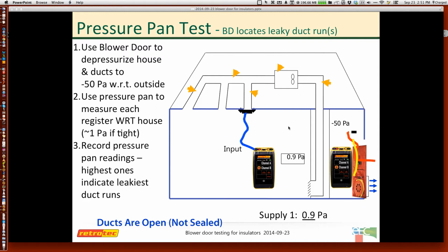If you're looking at existing homes, a lot of programs out there that HVAC contractors actually use something very similar. They get the blower door going, and then they go around and determine which ducts are leakiest. And they feel as though many times you don't need to do an actual duct test when you know where your significant leakage is, and you now know where to focus because you're going to seal the ducts anyway. So now I actually know that I may have more potential issues in some spots.